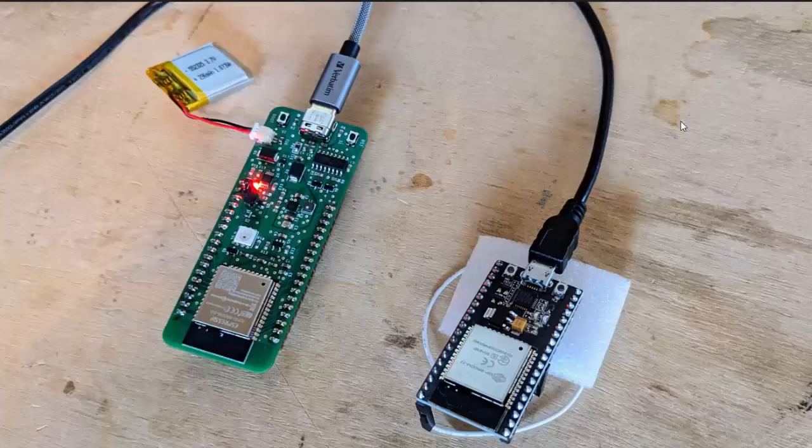So I'm going to start out with a pretty simple demo, right? We're going to look at some code that does a basic implementation of ESP-Now, as well as some functions to deal with MAC addresses. The idea is this code is a simple example, but we'll use it as a foundation for part 3. Now I'm showing you pictures of 2 different boards that have ESP32 modules on them. The one on the left is going to serve as our primary node for this example, and the one on the right is going to serve as our secondary node. Of course, when we get to part 3, we'll be able to support up to 20 secondary nodes.